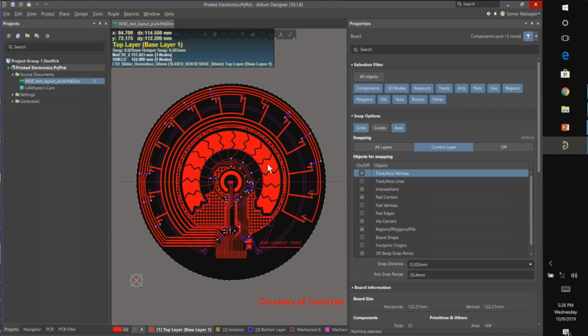We've actually had pattern generators to do that a while ago, going back probably 10 years, where that's pretty typical for touch sensor control, where you have these strange polygonal shapes, and they're all tied together. And basically, as you run your finger along that, the natural capacitance provides signaling to a controller that can then take some action. So let's say you want to dim lighting, control the volume, any type of thing like that. One of these sensors fits the bill pretty well.